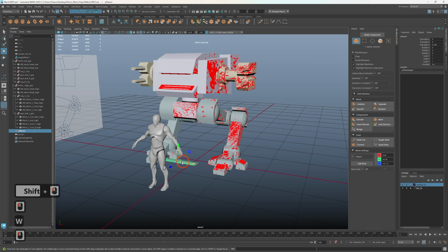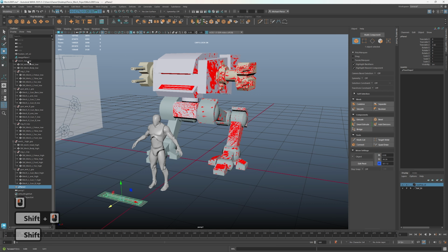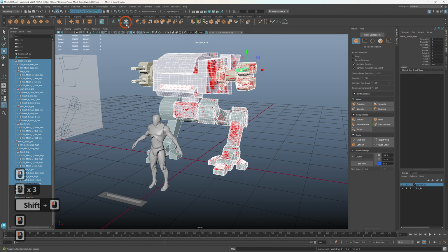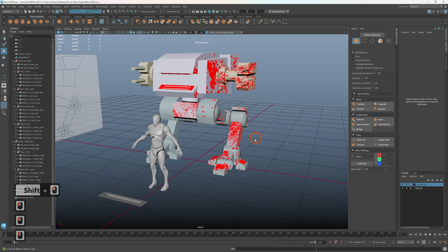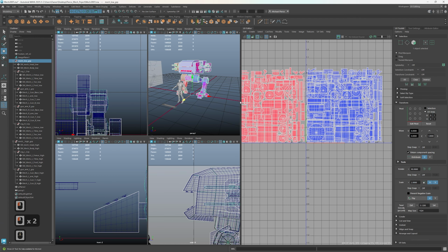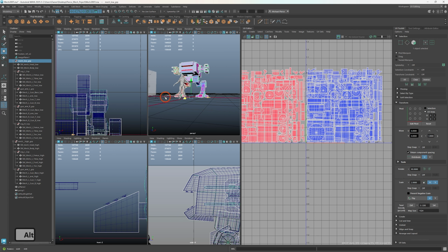and then just grab everything. In fact, I'm just going to make sure that we've got that there. Delete and freeze its transforms. That way everything's sitting where it should be. Check out our quick UV map, making sure that anything that is duplicated that we don't want to bake is on the side over here outside of the 0 to 1 space, since that's where all the stuff for Substance Painter is going to work.